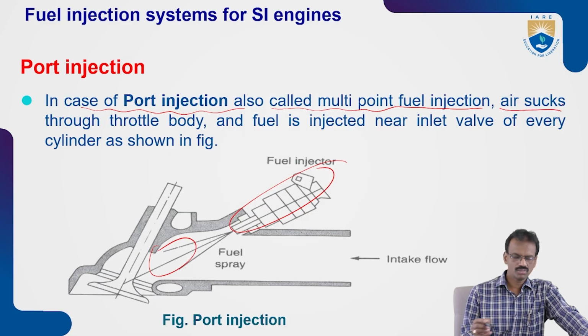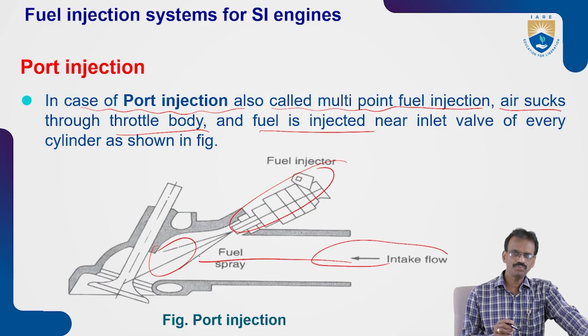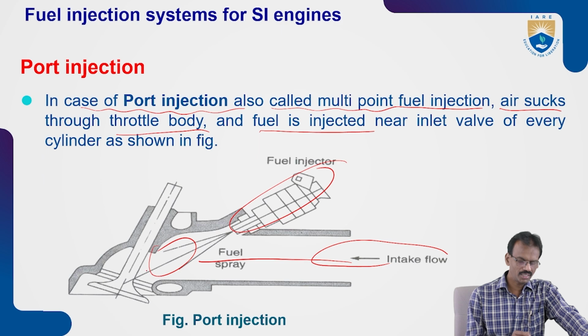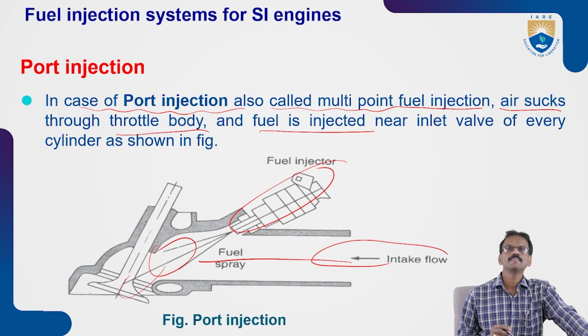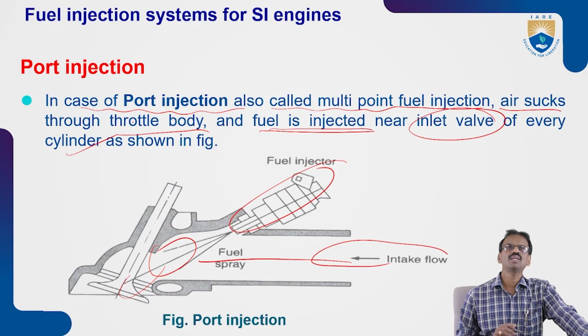Here, air is taken through the throttle body, and only fuel is injected very near to the inlet opening, near the inlet valve of every cylinder.